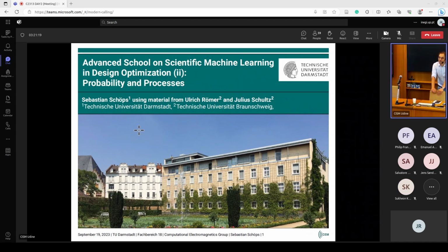The only case where this kind of data makes sense is if you realize something went wrong during your simulations, and it's very difficult from post-processing quantities to understand what went wrong. In the simulation picture, a trained engineer sees immediately, oh, okay, the boundary condition was set wrongly. Clear, I have to do it again. That happens. And this is almost impossible to see from a quantity of interest, or very difficult. These are the cases, but otherwise I only see it for debugging purposes. Even if you do the small one, it doesn't change the point that somebody has to look at it.